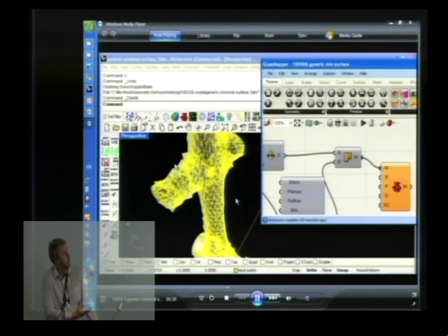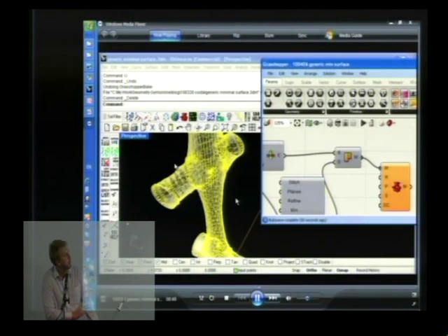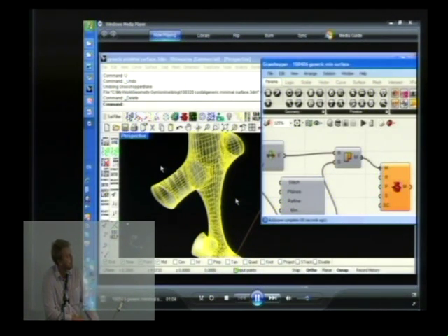So this is a force density or dynamic relaxation routine. And what you'll see, again, like an evolution process, etc., this is just a linear solver, though. It's getting a better answer each time. So the nodes are effectively dragging each other around the surface until you see it start to take shape and produce a smooth, continuous surface. Okay, obviously the movements get smaller and smaller until it converges on an answer.